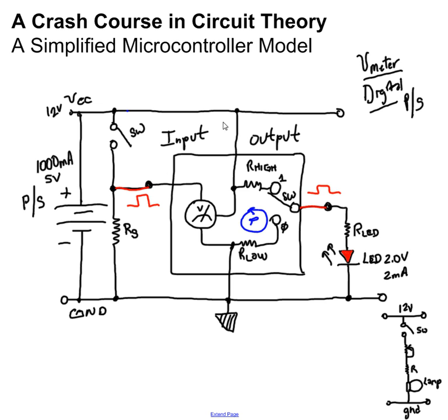However, since we are using the microcontroller as a control unit to switch the devices on and off, if this current passes through the microcontroller, there are limitations. There are some very sensitive circuits inside the microcontroller, and as you know, the microcontroller is a very small component, and if too much current passes through it, then it will become too hot and it will burn.